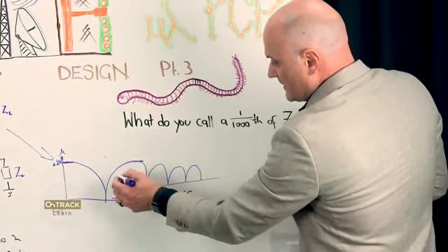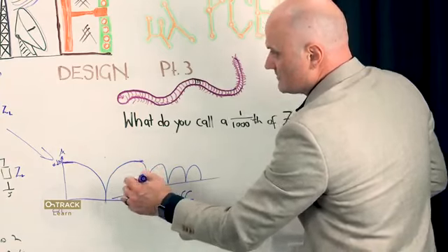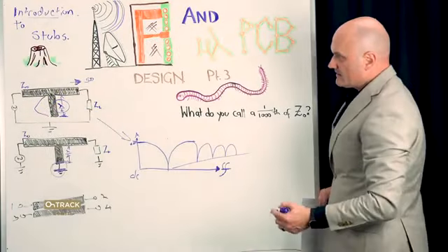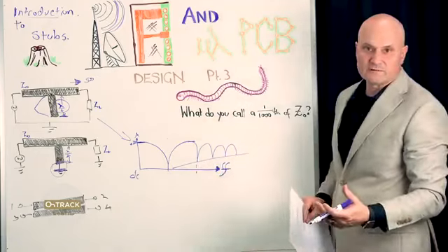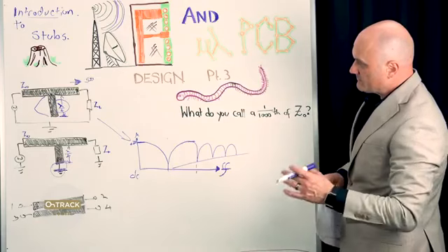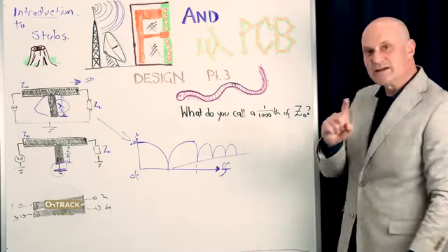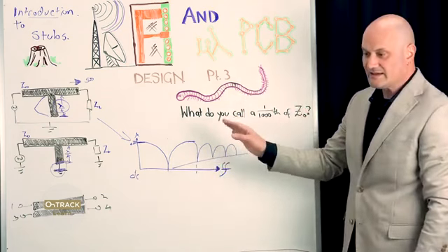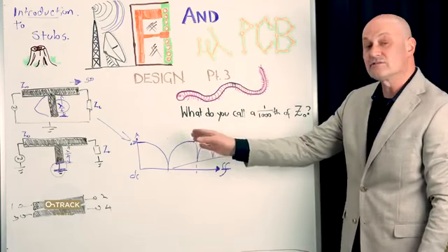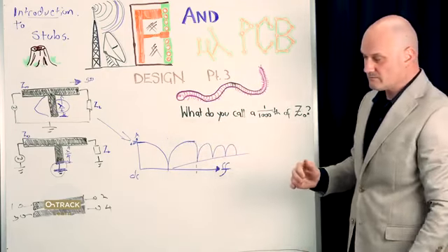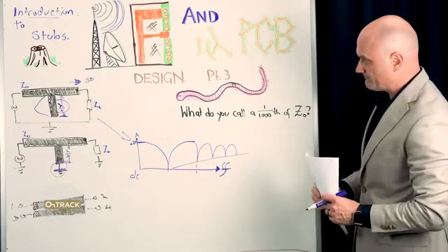It's because you're getting closer to some frequency where this is actually a multiple of quarter wavelengths, or some reasonable fraction thereof. And so just be aware of that, because you'll be designing a circuit for one frequency and you might discover that it's taking effect at other frequencies and letting things through that you didn't think it would let through, which is more often the problem, transmitting something you don't want to transmit.